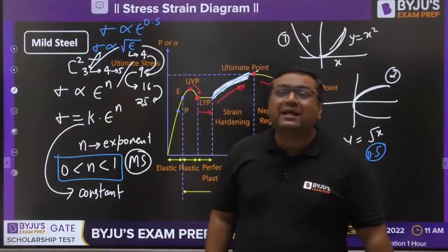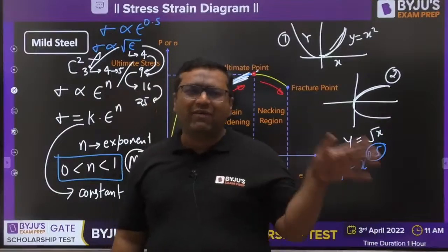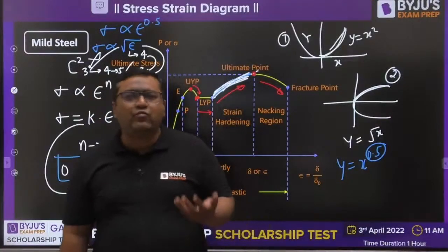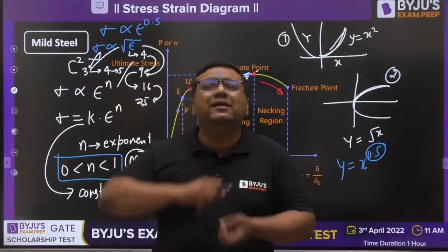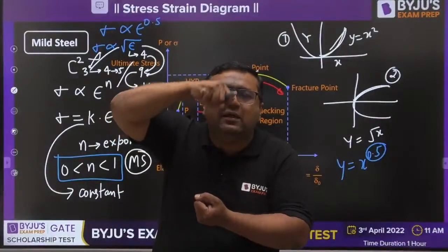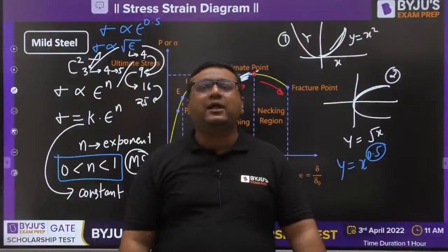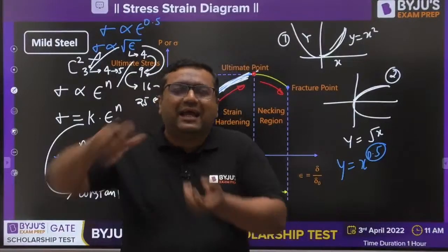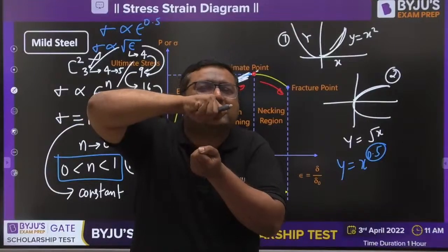So my dear, when this test is performed, the work of the machine is not to increase the load all the time. It is not linearly or parabolically increasing the load. No, the target of the machine is to give a constant deformation rate. Like I want to expand it 3 mm per second.